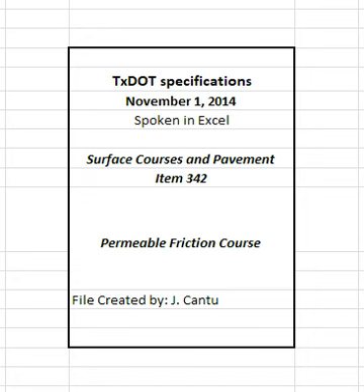4.4.2.1.8 Boil test. Perform the test and retain the tested sample from TEX 530C until completion of the project or as directed. Use this sample for comparison purposes during production. The engineer may waive the requirement for the boil test. Add lime or liquid anti-stripping agent, as directed, if signs of stripping exist.